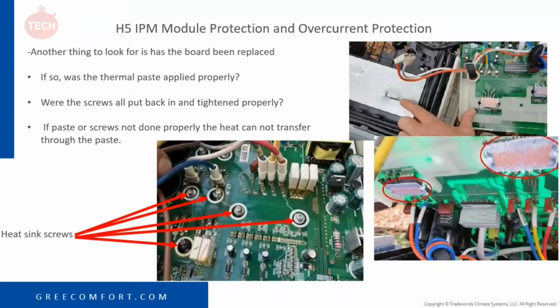Another thing to look at would be, has the board been replaced? If the board has been replaced, as you can see in this picture here, I have all the red arrows going to these screws that connect the board to your heatsink. These screws are crucial to get in all the way and make sure they're properly seated. As you can see, these are barely in, so of course it's not going to be able to dissipate that heat from the board to the heatsink.